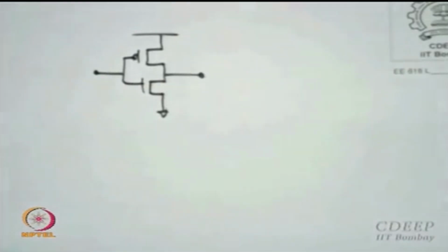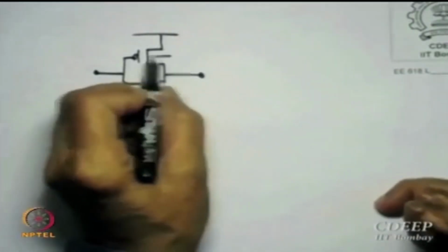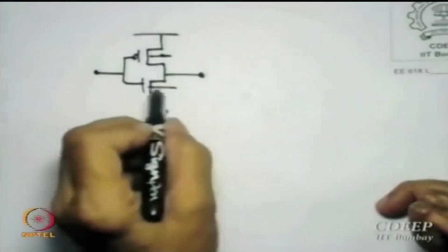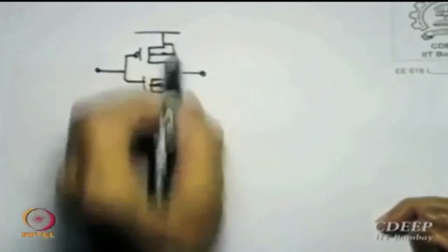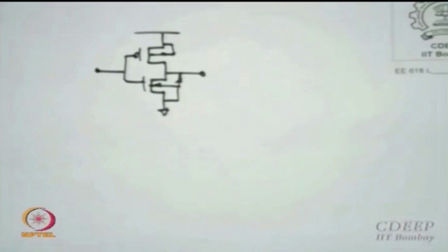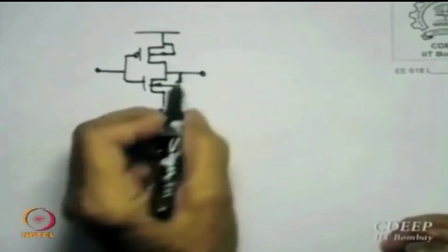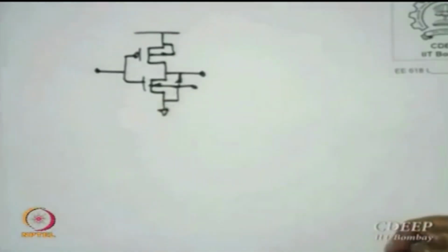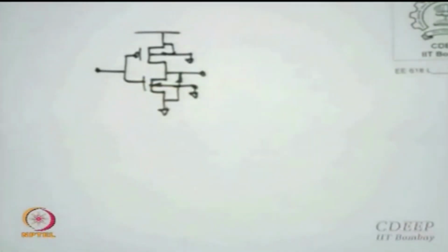What I see there is that the bulk for P channel and bulk for N channel are normally connected to sources. But in most circuits these days, because we want to control Vt through bias, what we do is either leave this separate or at best ground them. Is that clear? Now if we ground, because that is what control we need,